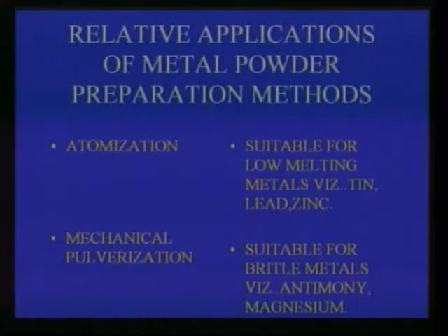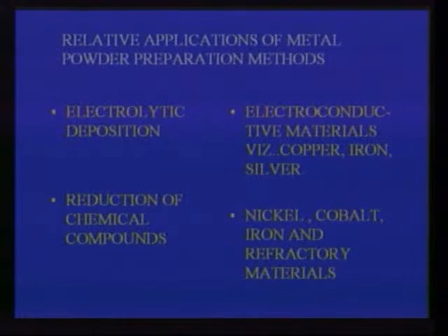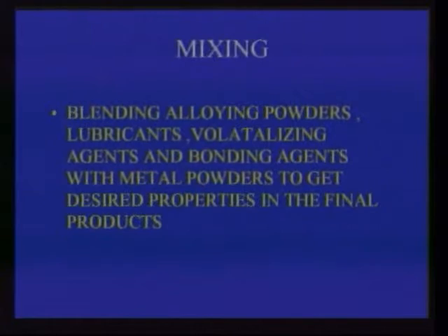Atomization is suitable for low melting metals like tin, lead and zinc. Mechanical pulverization is suitable for brittle materials like antimony, magnesium. Electrolytic deposition method is suitable for electroconductive materials like copper, iron and silver. Reduction of chemical compounds is suitable for nickel, cobalt, iron and other refractory materials.